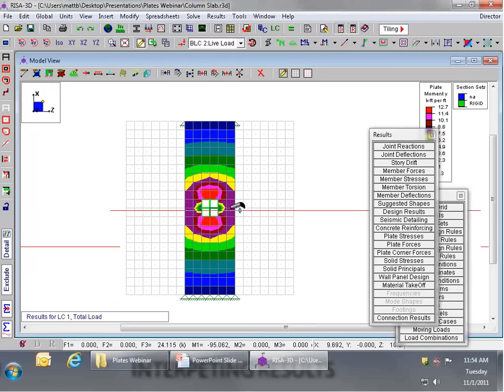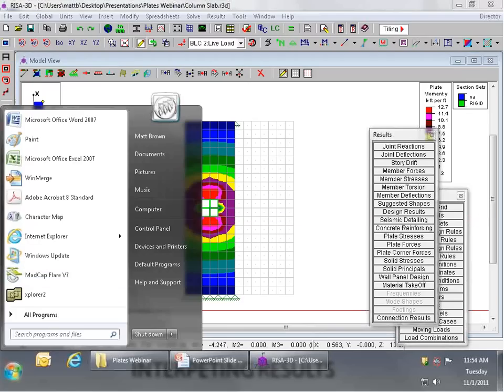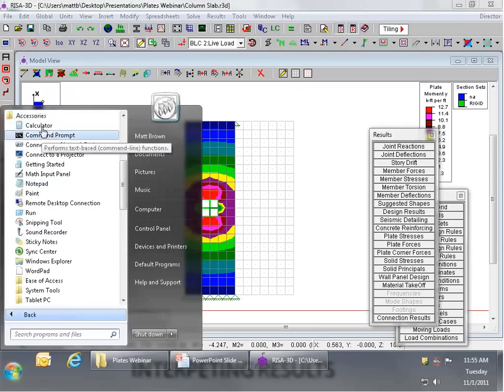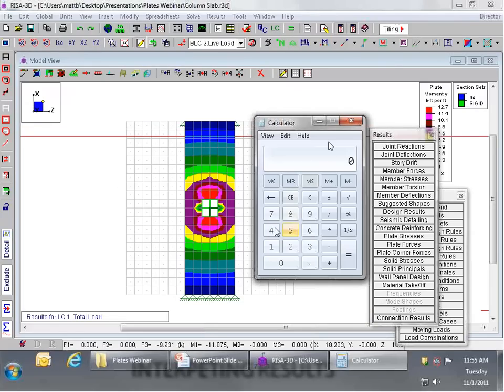And so once we get past that, of course, these values would represent what the moment is directly underneath the column. But remember that you're really only going to design the rebar for what's occurring at the face of support here. And so we're still sort of doing all this by hand. And so if I have a 78 kip-foot moment over this whole strip, what I'm going to do is just use the old-fashioned conservative method of designing rebar for bending, which is the Mu over 4d method. So if I have my ultimate moment, 78 kip-feet, divided by 4, and then we're going to divide that by the d of the slab.